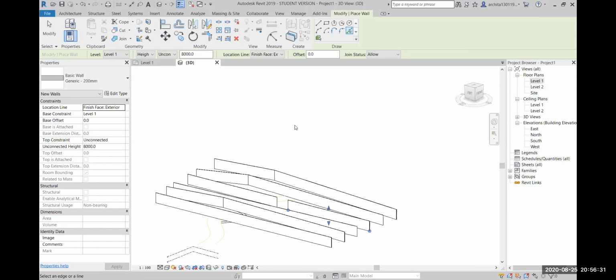If you want to take the reference from the CAD file, if you're making the drafting over here only, then there's no problem. Okay. So ma'am, after linking the CAD file, even if I make any changes in the CAD file, it will be automatically done here? Yeah, you just have to close both the files and reopen the Revit file again. Save and close the CAD file. Even over here, save and close the Revit file and then reopen it. So basically you have to close it so that the linking can be done. And once the linking is done, open it and then you will get the updated CAD file.